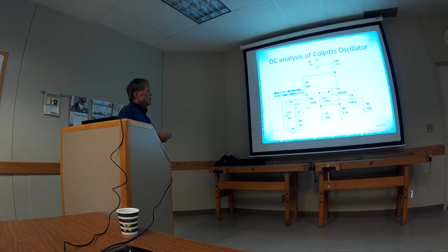So you see the bias is really going to be 12 volts times this resistor divider. So you take R2 over the sum of these two, R1 plus R2, so you get 12 times 120K over 202K. That's about 7.1 volts. Now it's a little bit different because this is taking off a little bit with the base current going through there, but it's very close to 7.1.